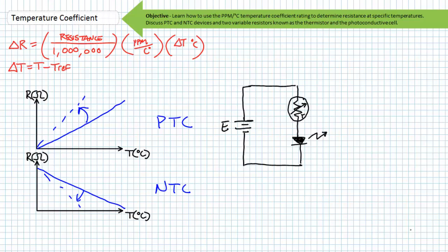Consider a temperature indicator light, in which a PTC thermistor, i.e. one where resistance increases with an increase in temperature, is employed in series with an LED, or light-emitting diode. It's like a diode with light beams shooting away from it. It's similar to a lamp, except conventional current can only travel in one direction, signified by the arrow on the diode.